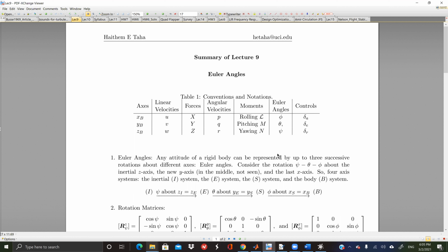So in this regard, when I have the disturbance here, what is the angle disturbance along the pitching? What is the disturbance angle? Of course, we're not talking about the Euler angles. We're talking about the aerodynamic angles, right? What is the aerodynamic angle in the pitching? Can anyone give me what is the aerodynamic angle in the pitching? Alpha. Alpha, right? So then the restoring moment M due to alpha, this is stiffness. The same here, the restoring moment N due to the corresponding angle, which is beta. This is yaw stiffness. The same for roll. L due to beta is roll stiffness.